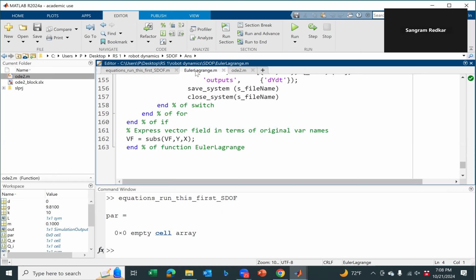So you will find out the rotational and translational velocities of each link. You will find out the rotational and translational kinetic energy of each link. You will add all that, and that gives you your total kinetic energy.